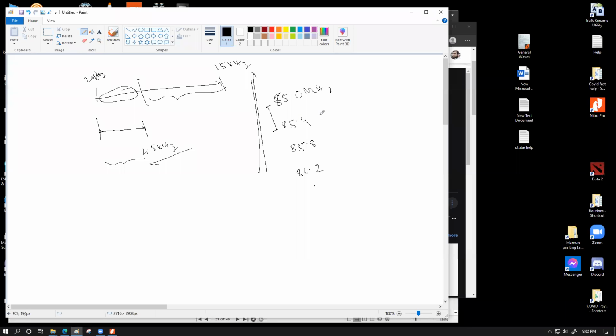This is because, like I said, each station has a bandwidth of 200 kilohertz. So that is 0.2 megahertz. So this one plus this is the bandwidth. So this one can have a variation from here through here. So we have a total of 100 kilohertz over here. I'm going to write 0.1 megahertz on one side and 0.1 megahertz on the other side.